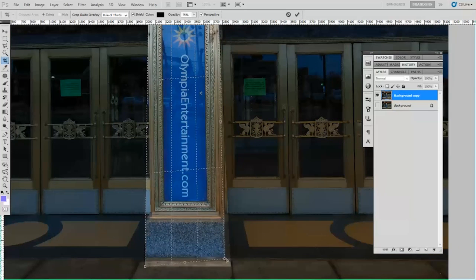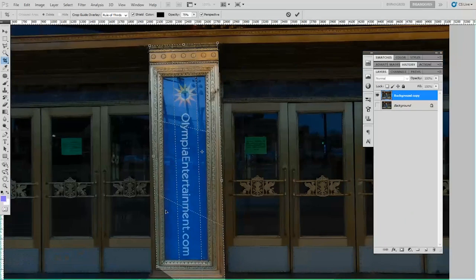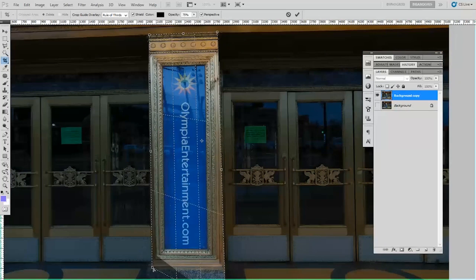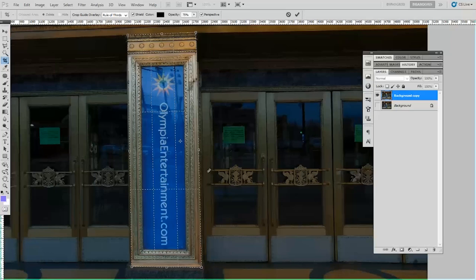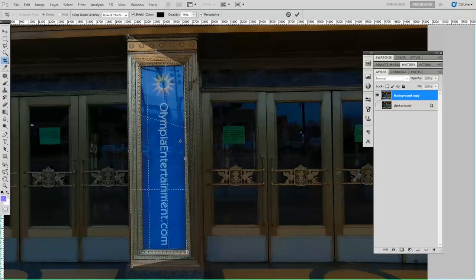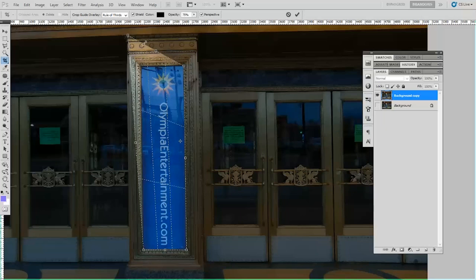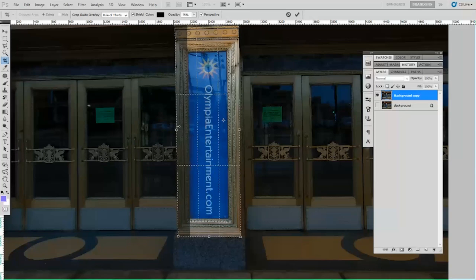going by the top line, and then I'm going to take this, and you basically just want to line it up to the perspective of the image. So all these corner lines are going to be lines, but that's not going to work because it's not going directly to that plane or perpendicular to that. So we're going to move it up to here and make sure that it's lining up with our top lines as well as the bottom ones. And a little trick I learned a while ago, if you match it up to something else, like this blue window here, that we know is exactly the same perspective. It's a fairly easy concept, but if you have like one corner wrong, it's going to mess up the whole thing. So you really got to make sure, bring out the edges, and then just hit the check mark for that.